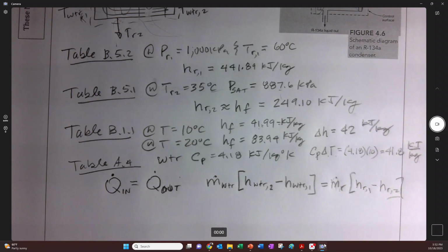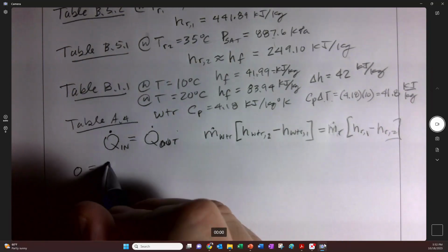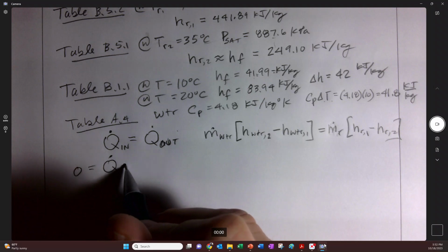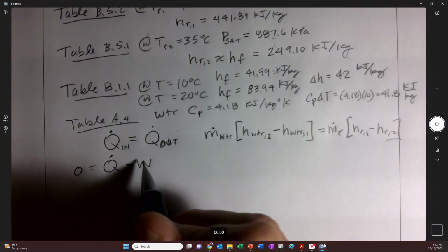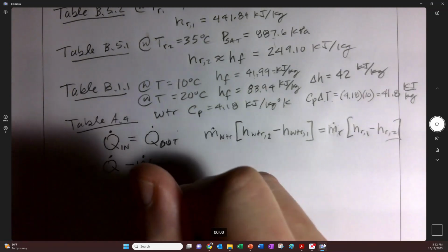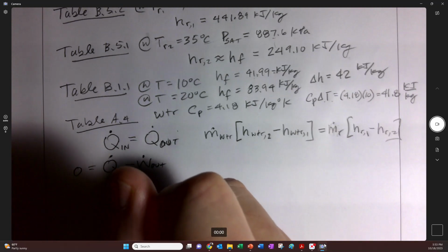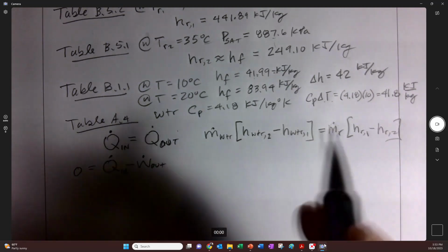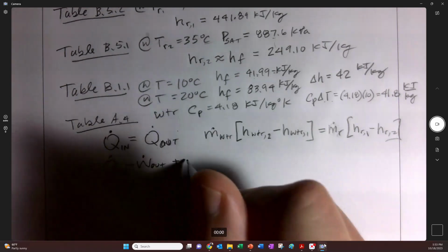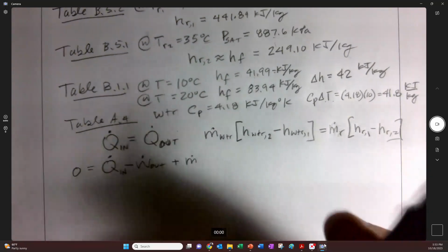Another way to think of it, right? So let's go back to our big equation here. We're going to go equals Q dot, and that means Q out most of the time, minus W, and this is Q in, W in, right? Out, excuse me. We'll go out. And this is in, yeah, because this is normally a heat engine, so we're good there. And then this equation usually goes plus m dot, or they go summation of m dots.